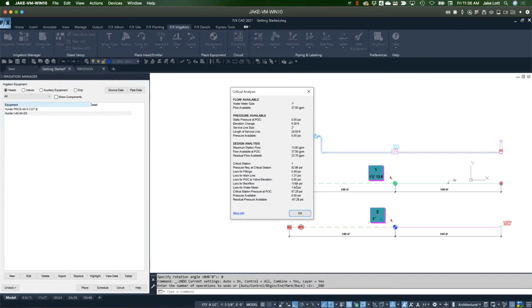And I really take irrigation design as a whole to mean your design is your design. So if you've done your homework, you've done the right equipment, you're watering the site based on what it needs, understanding its watering days and all that kind of jazz, and it's still exceeding what you have at the demand, or sorry, at the source, then we need to figure out how to supplement that.